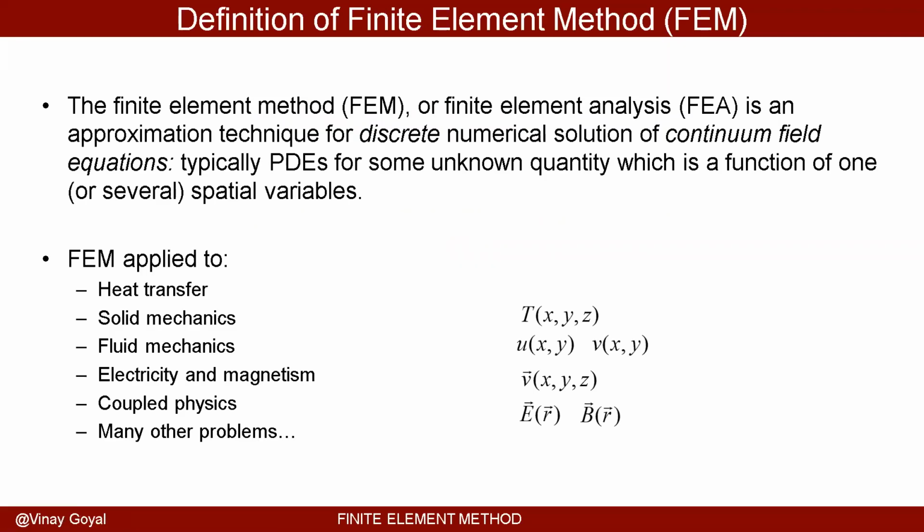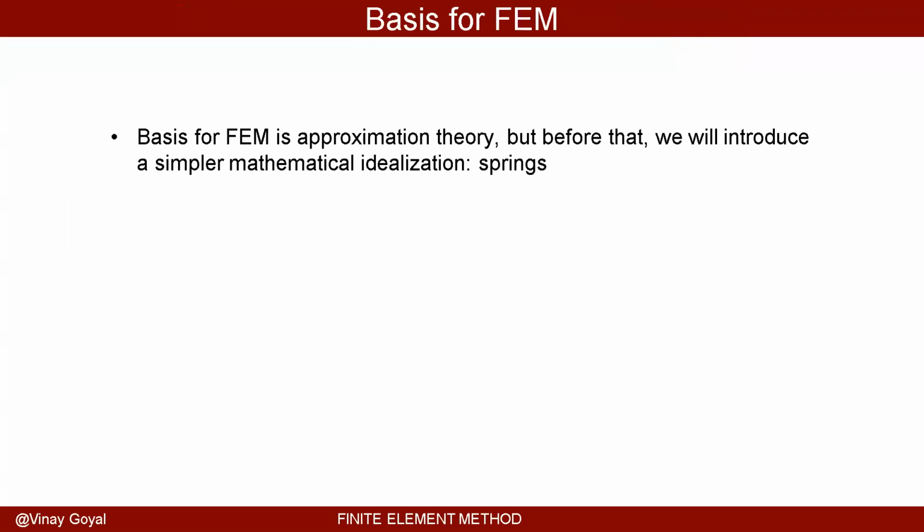Just to remind you, finite elements is a method that allows you to solve partial differential equations in an approximate way, and it can be applied to a lot of different fields. It works by discretizing the domain into small domains for which you can approximate the solution, and then you can assemble the whole thing together and form a linear or algebraic set of equations that can be solved for. The basis for finite elements is approximation theory.